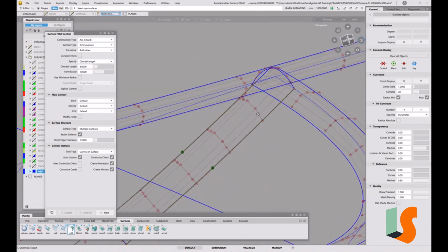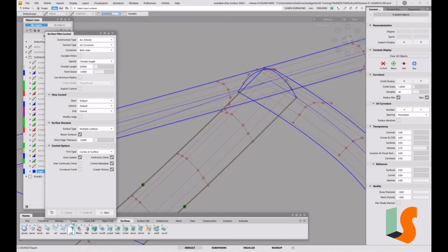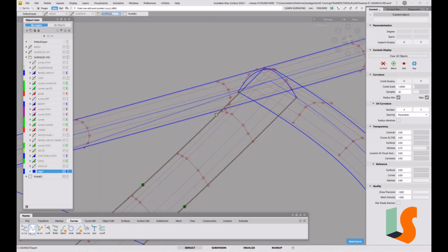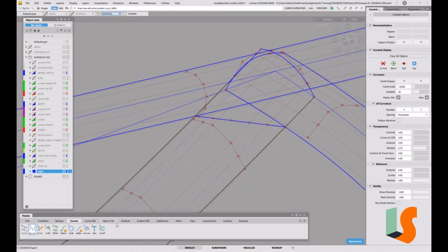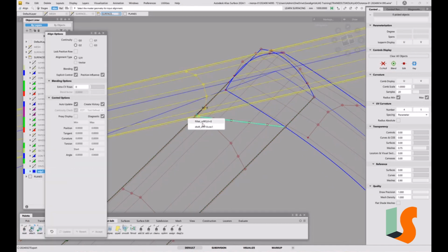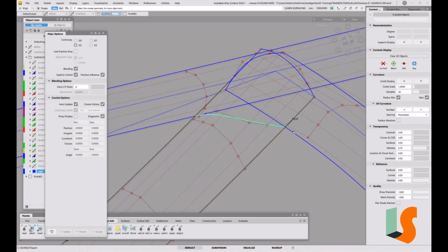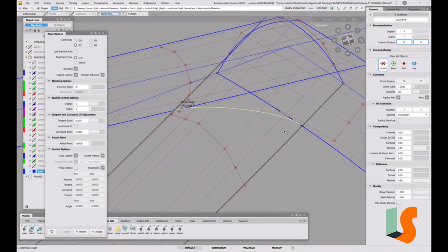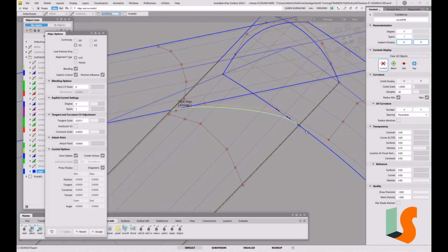So what I want to do here is put in a curve going from here to here. So I'm going to do an edit point curve here with degree 5. And hopefully we'll be able to pick up the intersect points there. This is the usual scenario when we're doing corners, and I'll make that G2 continuous into there and G2 continuous into there, checking we've got. We won't get one arrow on the end, of course, because it's not to an end as such, it's to an intersect.